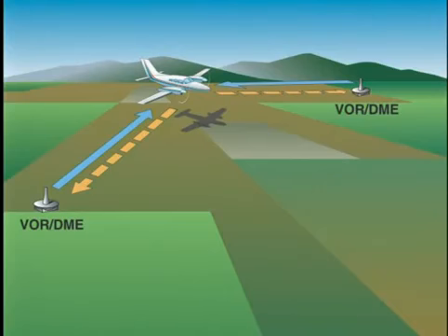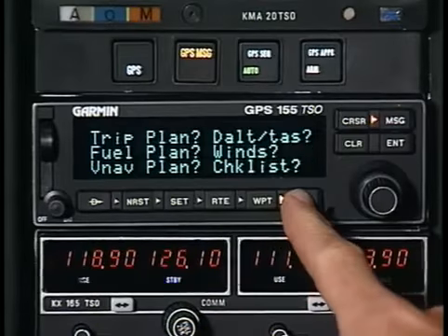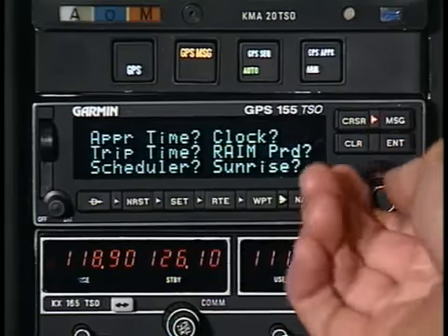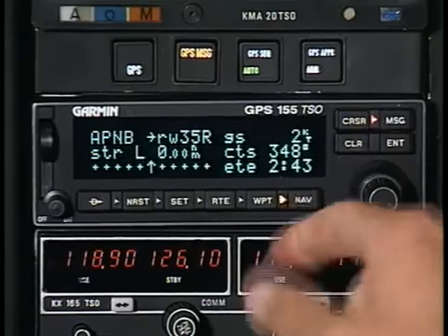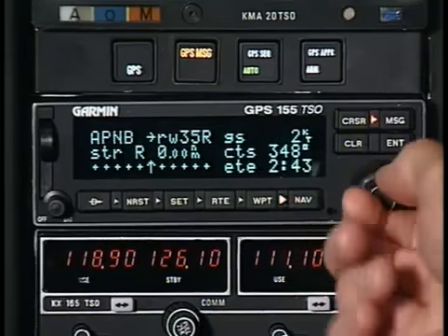Some systems calculate lateral positions based on DME readings. If your system operates by DME triangulation, you are unable to use the LNAV/VNAV minimums for the Yankee runway 15 right approach. Since every system operates in a different manner, you must have a thorough understanding of the operational capabilities of your GPS or FMS system in order to comply with these requirements.